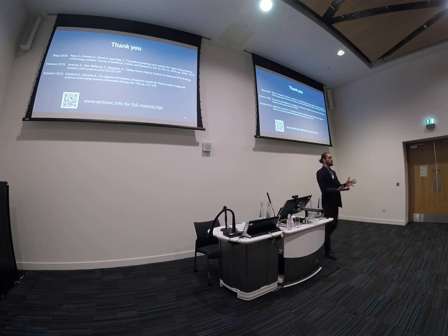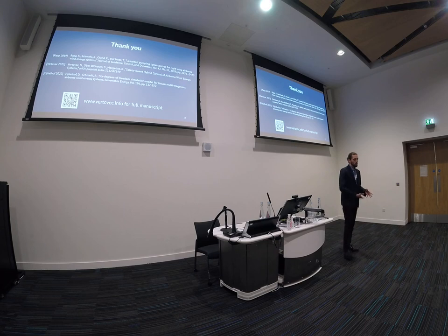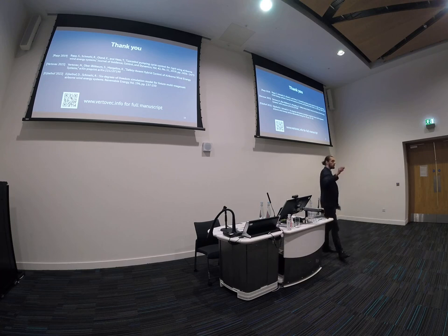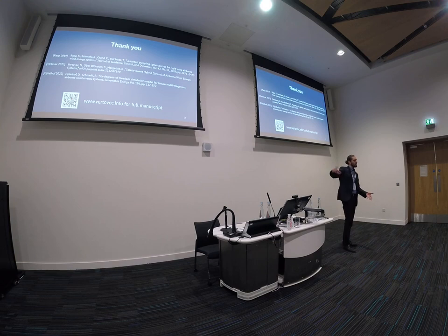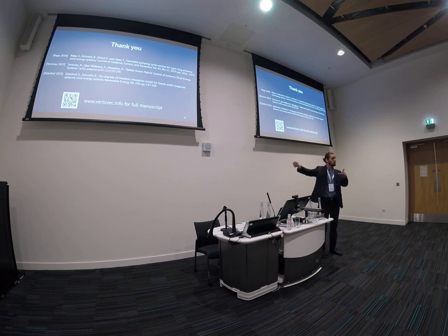Well, it is sort of important to impose it at all times, because what it ensures is that we're not only safe now, but we're also going to be safe in the future, and that with the control input that we're applying to the system, we're not walking into areas that we potentially can't get out of later on. Depending on your application, you can tune this gamma term to make sure that when you're very far within the set, it's effectively negligible. In this work, we used a gamma factor of 2, which is higher than average, so we're really only enforcing it towards the boundary. But the way that it's implemented, as a quadratic program, it works really fast, because most of the time it just checks the existing solution and says, yep, that's fine, move on. And so that constraint is only going to get violated when we're effectively at the boundary, if that makes sense.